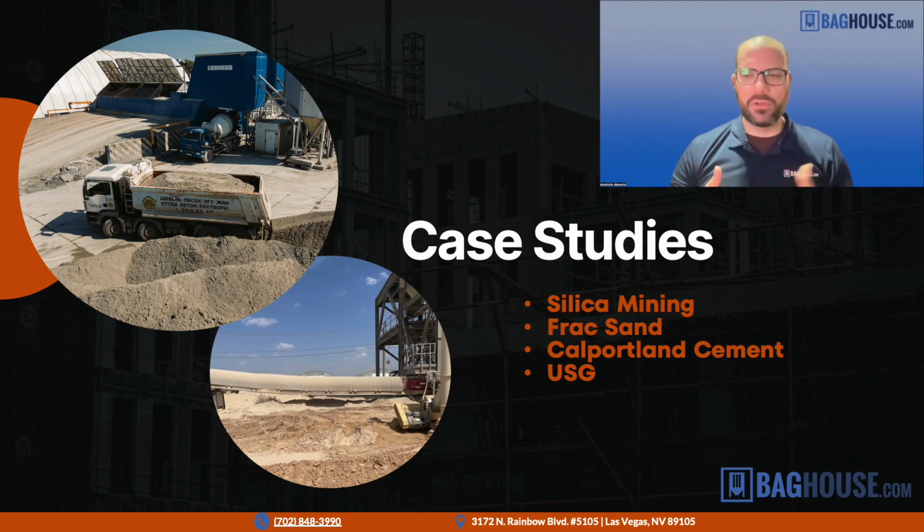A few other things that we've done with them in particular plants. We're working with one plant in particular to change many of their bin vent dust collectors. They have a dozen or more different manufacturers and legacy units, designs in their plant, which makes finding parts and maintenance just a nightmare. So as we've been replacing them, we've made a concerted effort to make sure that all of the bin vents are the same design and take the exact same parts, exact same filters, exact same pulse valves, controllers, all these kinds of things.